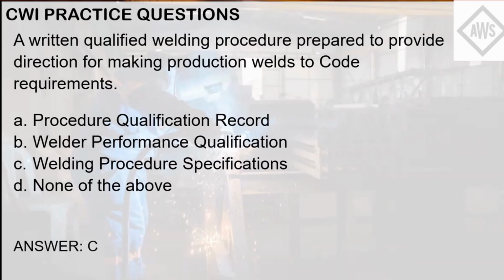This welding document is like a recipe or a written step-by-step procedure that is used by the welder in making sound production welds. So this is the document that the welding inspector should refer to as well in ensuring that the quality assurance documents have been followed at site, because this has been proven to produce sound welds.